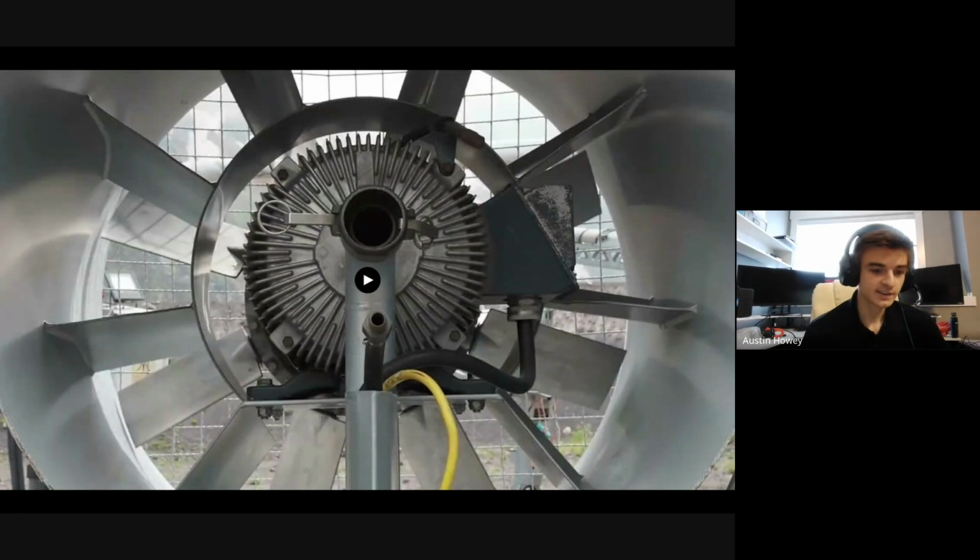Okay, so I imagine everybody got the general idea of that. The way that this works is there are different types of bearings, and this right here is an insulated bearing. The internal components, in other ones, would be steel balls, but in this scenario these are filled with ceramic. Ceramic is very durable and it's non-conductive. So when you run electricity through ceramic, it's not going to do anything. But if I run electricity through metal or copper or anything like that, it's super conductive. So that's another thing you have to pay attention to.